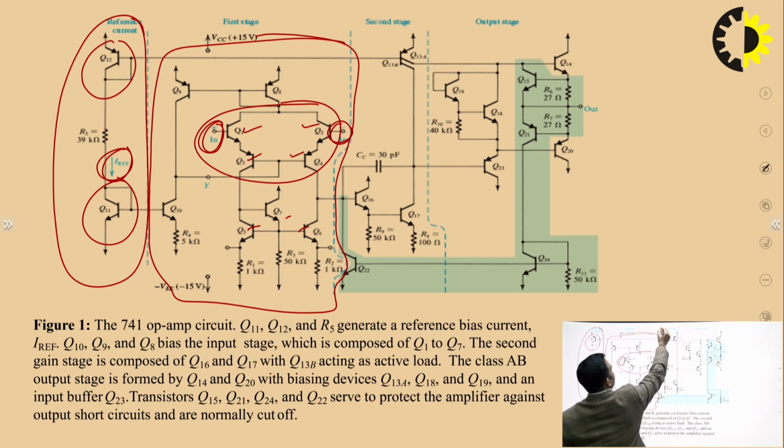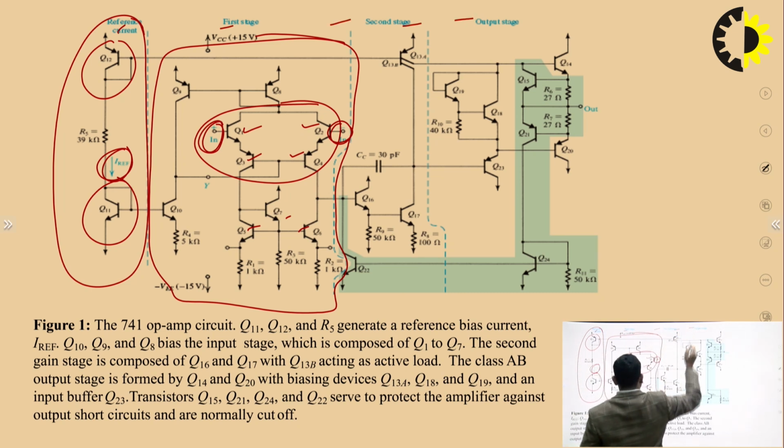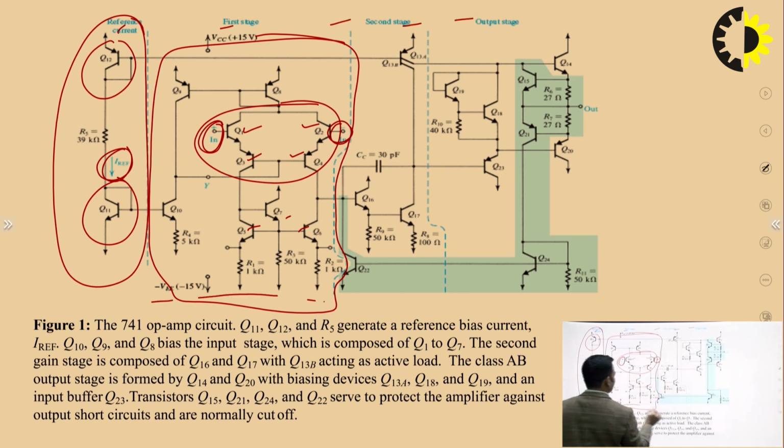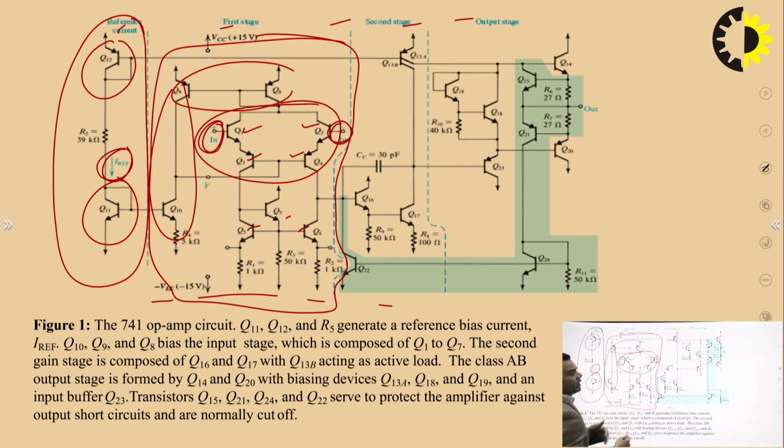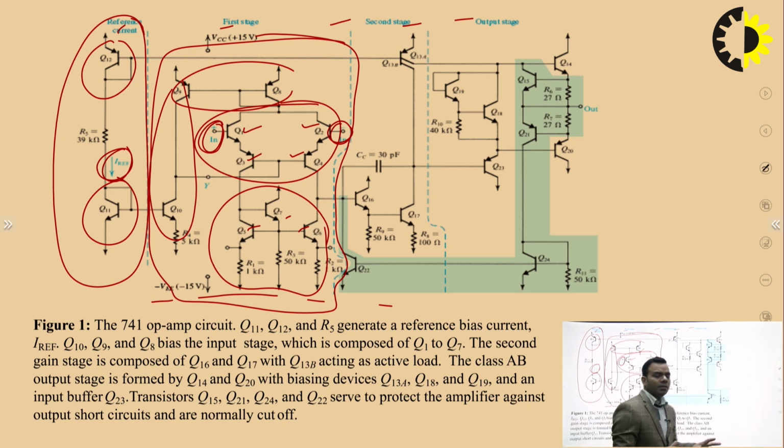If you see, these all are connected to positive voltages and these all are connected to negative voltage minus VEE. And this is the current mirror, this is again a current mirror. They will provide constant current or biasing current for the operation of this circuit. And these 3 transistors Q5, Q6, Q7 and these 3 resistors, they whole will work as an active load.